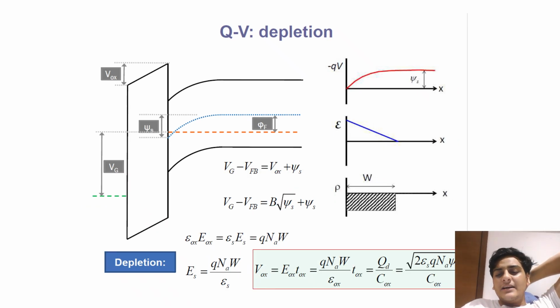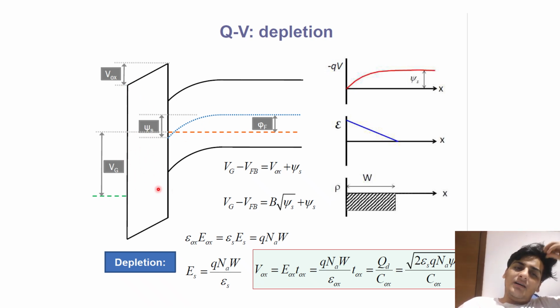The next thing that I want to bring to your attention is that this oxide behaves essentially no different than a capacitor. So you can think of this exactly like a capacitor. And a fair warning again, the symbol here we use, C ox or capacitance of the oxide, is again per unit area.